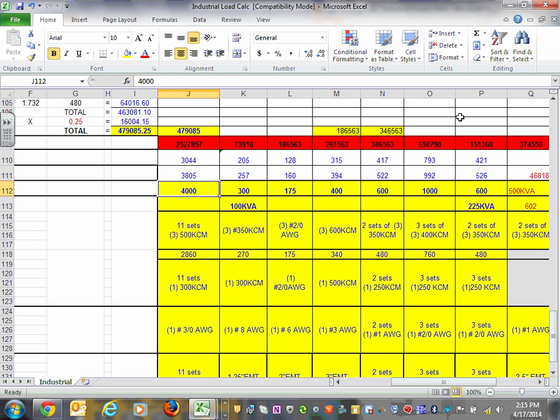There's a plug that you can do. There are settings that you can do on them. So keep in mind, if your system is 1,000 amp, 99% of the time as an engineer you will be dealing with almost fully electronic adjustable circuit breakers. They can be molded case, fully adjustable, or they can be like our switchgear, draw-out type circuit breakers. It doesn't have to be; it could also be molded case adjustable circuit breakers. 1,000 amp or higher is a good application for it. Best application. A good application is 600 amp or higher.